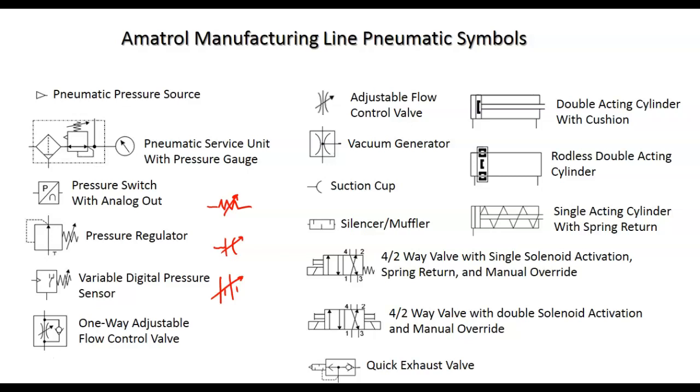So a variable pressure regulator, that's this gray knob you pull out and you turn. By the way, most of the time you can't just turn a pressure regulator's knob. On most of them you have to pull up, then turn to whatever pressure you want to regulate, and then snap them back in. And that's true on all ours.